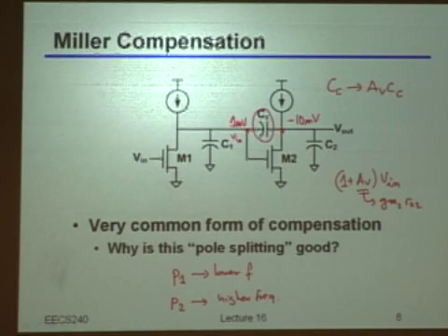And because I've placed this capacitance between two spots through which I have a potentially high gain, we have now explained why the dominant pole goes to lower frequencies: indeed, the CC gets basically translated at the input, amplified by AV. And so there is a dominant pole that gets shifted to lower frequencies.